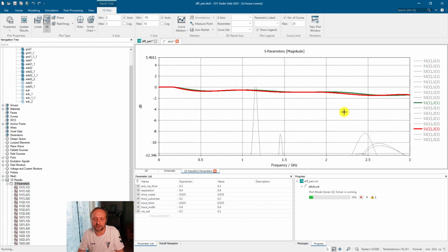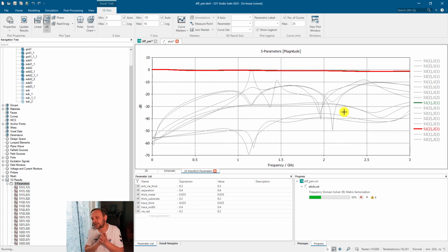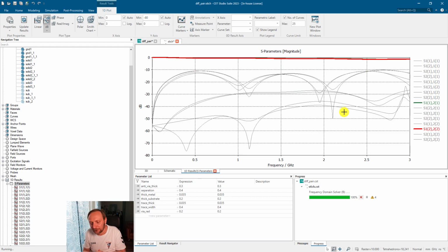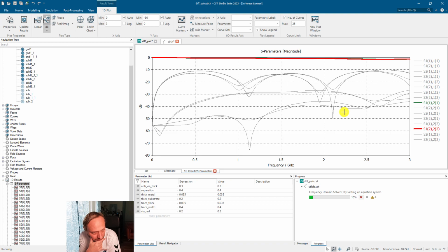You might ask yourself, why is the guy in SI talking so much about common mode? My background is in EMC, and in EMC everybody talks about common mode, so I cannot get rid of my background and chose the common mode to demonstrate these differences with the stitching vias. Maybe signal integrity engineers won't look at this, but clearly, if you route your signal away from the board over a cable, you should keep a very good eye on the common mode.